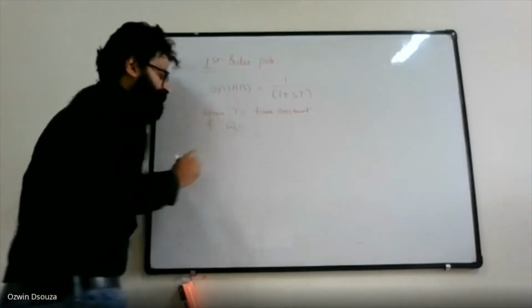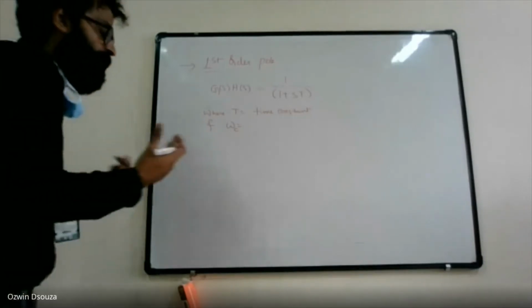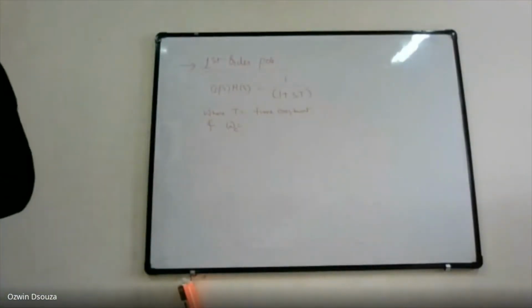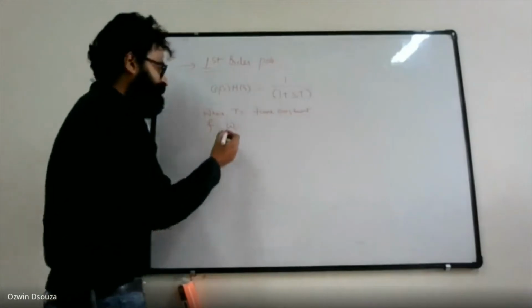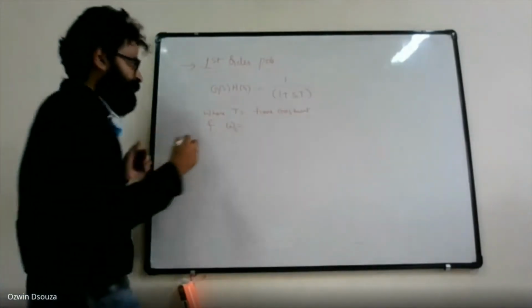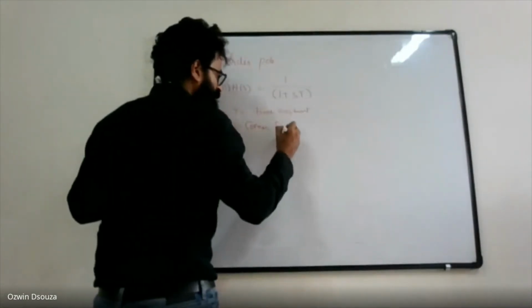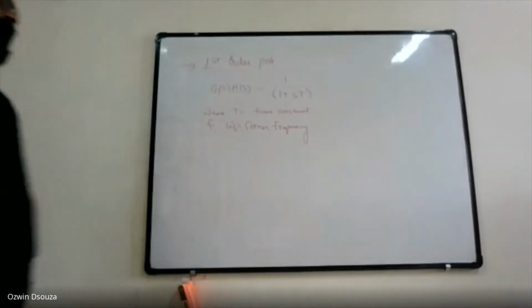And omega c, in control systems, is the reciprocal of T. In normal terms, the reciprocal of T is frequency, right? So let's consider angular frequency, and we'll give this suffix c also. That means omega c is called the corner frequency. A particular name is given for this frequency, that is corner frequency.